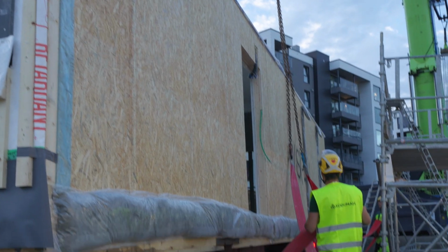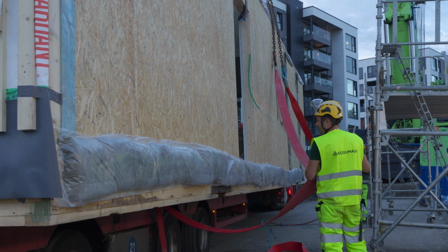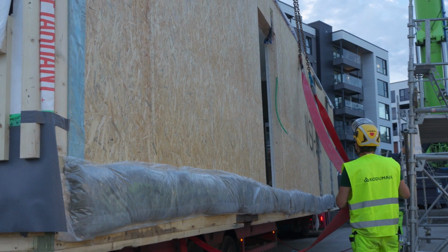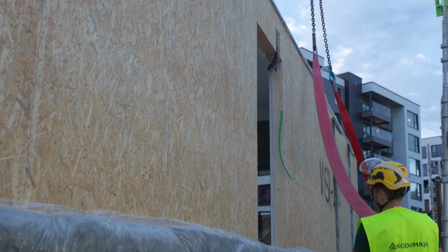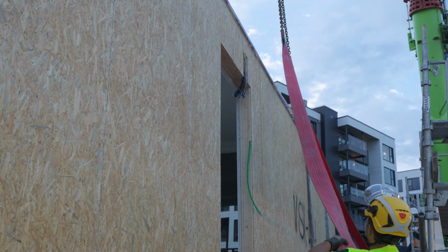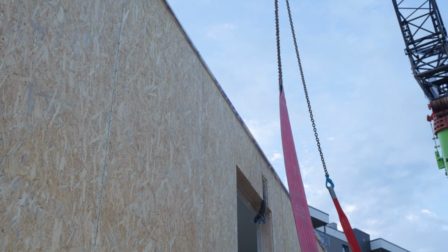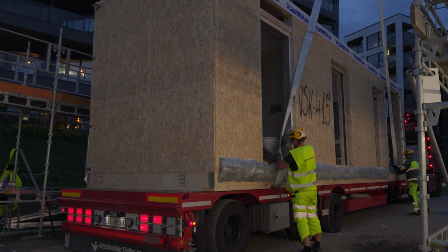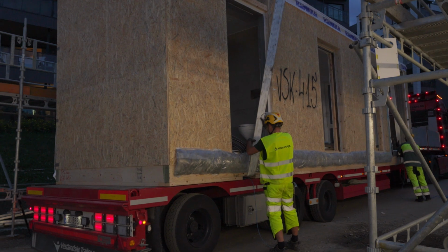For safe construction work, workers involved in lifting operations must have completed a rigger training. Foreign workers involved in lifting tasks must have completed an international rigger training. The workers must ensure that the load is correctly placed on the lifting slings. The volumetric elements have designated locations for lifting straps, and a spreader beam is used for lifting operations.